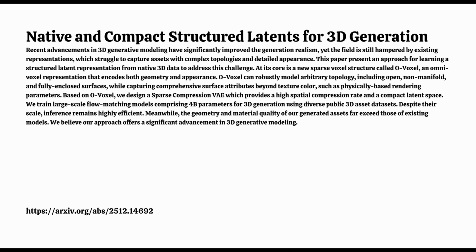That seems much more direct than trying to fit a field around the whole object. Yeah. But how does it determine the final position of the resulting vertex in that dual grid? The new corner of the mesh it's extracting. That's where the power of the QEF comes in, the quadratic error function. A standard QEF calculates the best compromise spot for a new vertex that minimizes the error to all the incoming Hermite data. It's like a group of surveyors all pointing to different spots on a wall, and the QEF finds the one best location that makes everyone the least wrong. That's a good way of thinking about it.